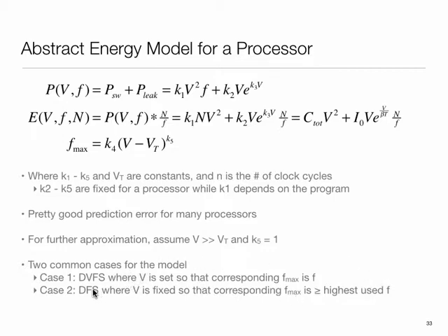The other possibility is the one which I was describing, which is dynamic frequency scaling. So voltage is fixed, and the frequency is selected to be Fmax or lower. Okay, and as we saw, it does not carry any energy advantage necessarily, but it can carry a heat dissipation advantage. It can carry a peak current advantage, and actually there is a third benefit it can have.